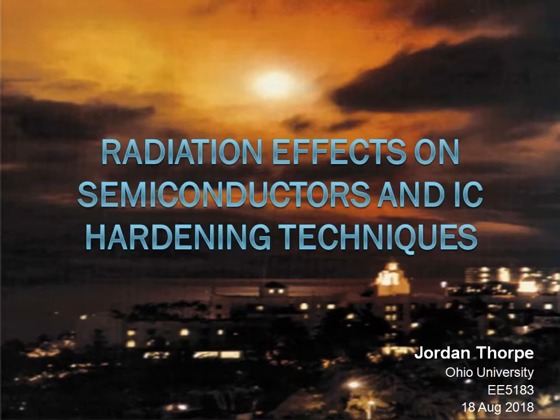My topic today is radiation effects on semiconductor devices and the selection of architectures, processes, and materials that can be used to help mitigate them. While there are various hardening methods out there, my focus today will be on the techniques used during IC design and fabrication.